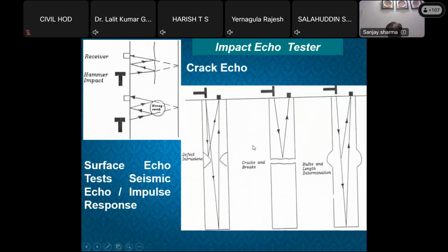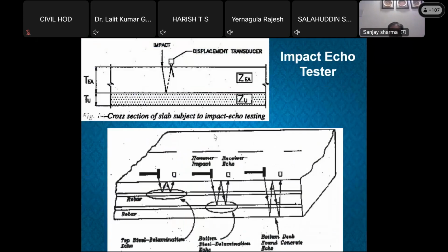So if I have 50 piles, you can test 50 piles in one day with this method and find out how many piles are fully penetrated and working fully, or not working. Whether a pile is okay or not, you can find out using this test method. Because doing load testing on every pile is very difficult. So you will be able to decide by using this particular method.